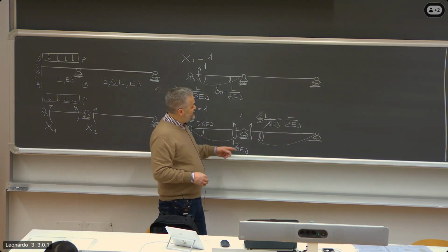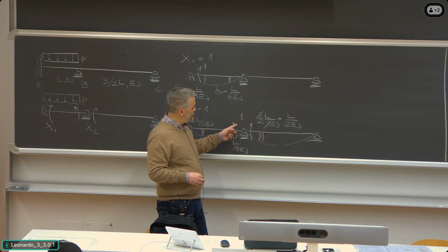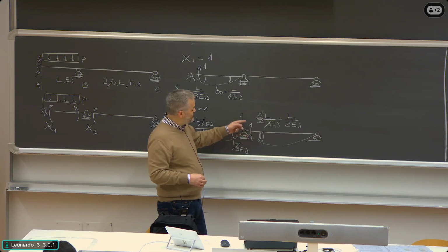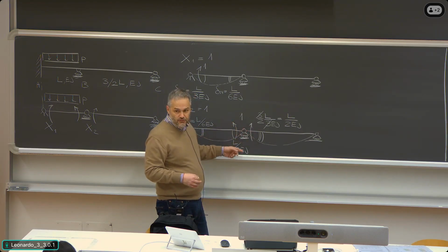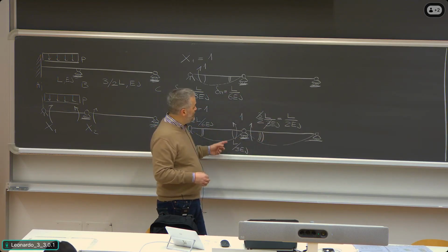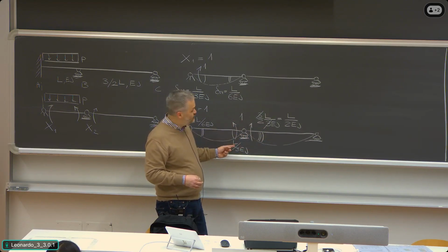And then for the delta 2,2, since we are looking at an internal bending moment, you can either write that the rotation to the left is equal to the rotation to the right, or you can look at the relative rotation when you then write the compliance equation. We do it in the second way, so what we look at is the total relative rotation induced by this moment.